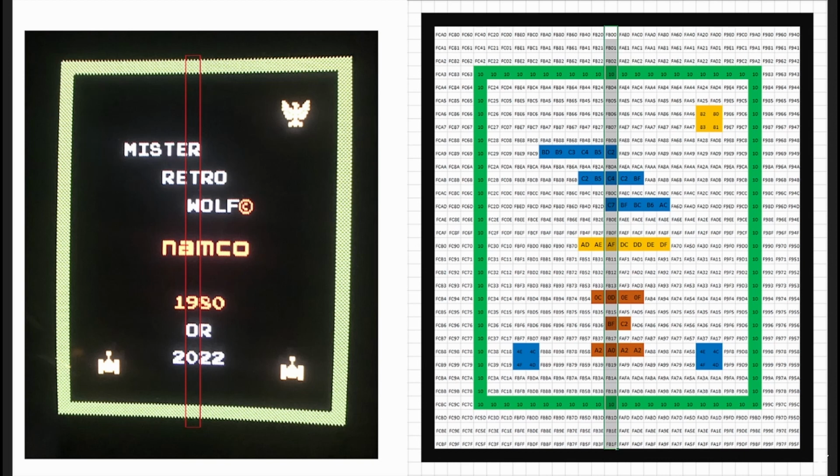In the last two episodes, we just implemented a simple circuit with just a ROM chip and a CPU, and the CPU fetched some screen data from a certain area in the ROM and wrote it to a virtual area of RAM. But of course we didn't have any RAM, so it was writing it to nowhere. So in this episode what we're going to do is we're going to actually implement that RAM. It's going to be called 0-page RAM because it's down in the low end of where the CPU sees.